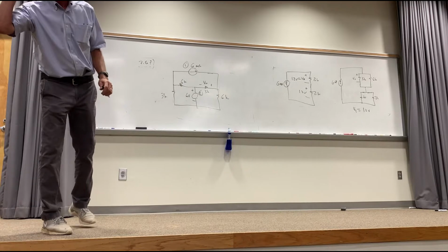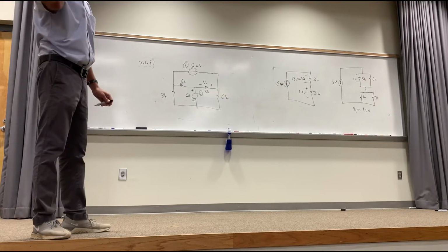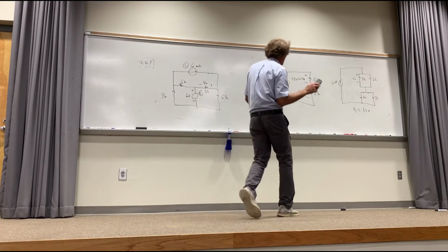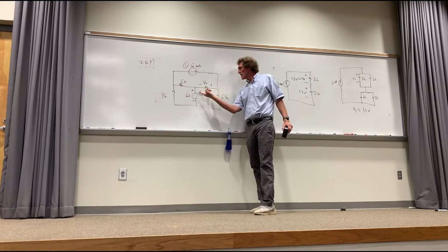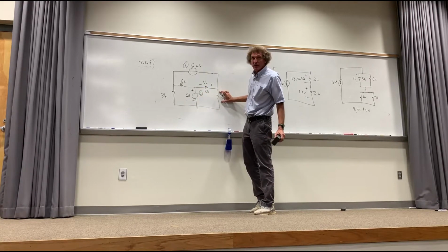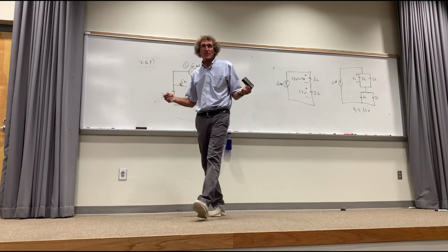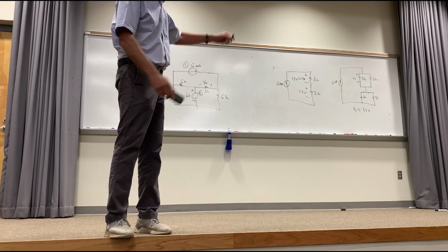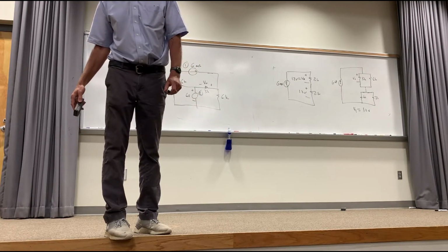Yes. I was asking, why didn't you add those resistors in series to make it 24 instead of 12? What? 2K resistors? Yeah, we wanted, see, the output is taken right here. We only want the output voltage across this resistance, right? That 3K is in parallel with this 6K, right? So either the voltage here or here, when they're in parallel, they're replaced by 2K. So that voltage is just going to be 2K times the current, which is the same in those legs, which is simply 6 milliamps, right? So when resistors are in parallel, the voltage drop.